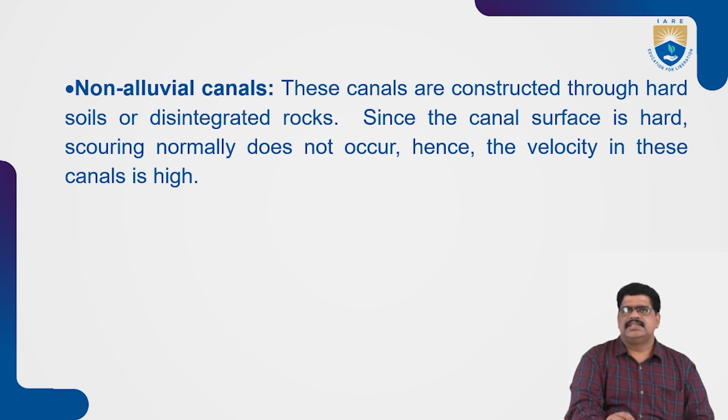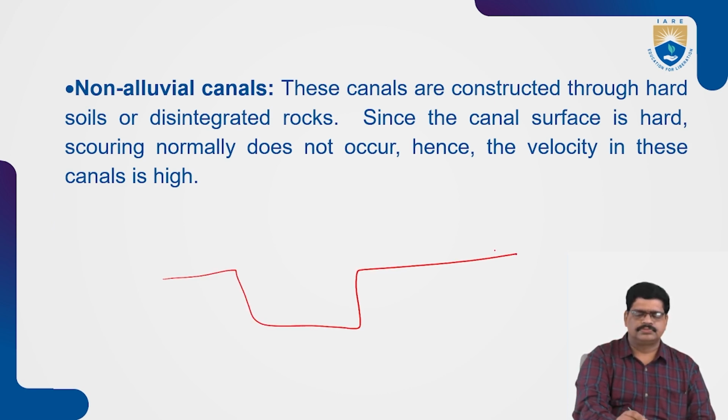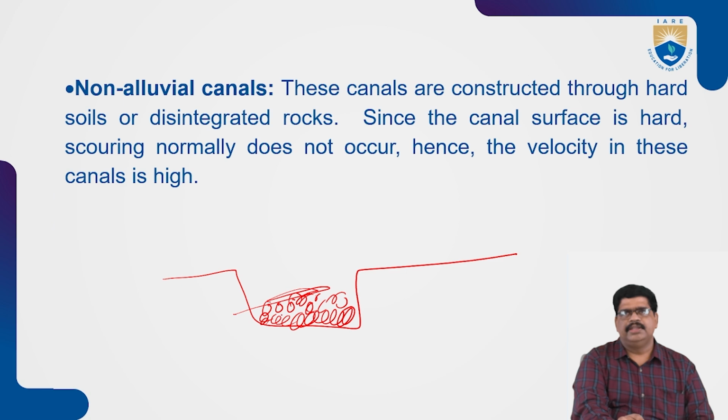Non-alluvial canals are canals constructed through hard soils or disintegrated rocks. This can be provided at the bottom since the canal surface is also hard. So from the hard rocks it can be provided. Due to the water flowing over the canal surface, scouring normally does not occur.